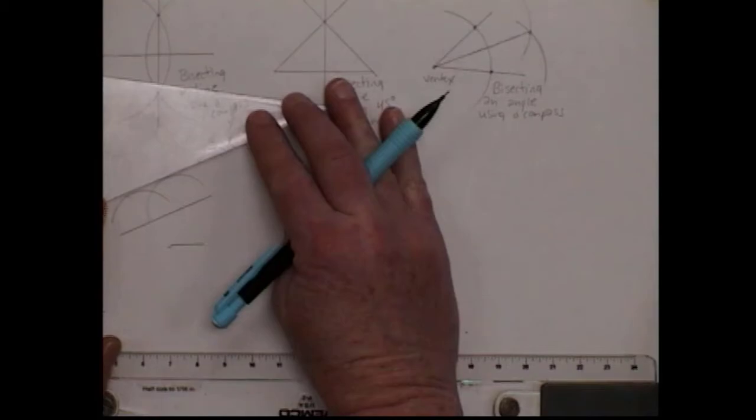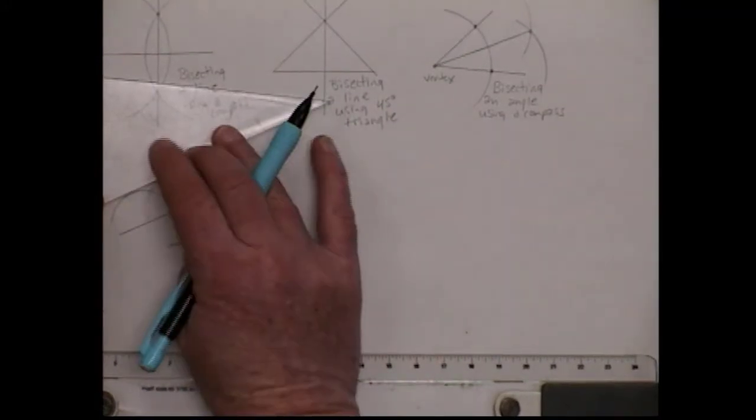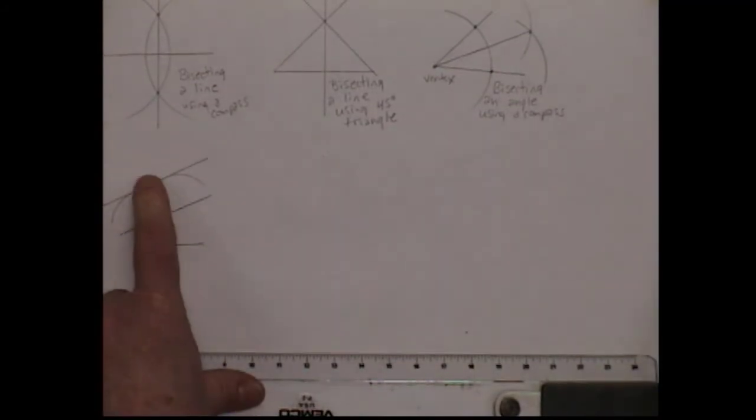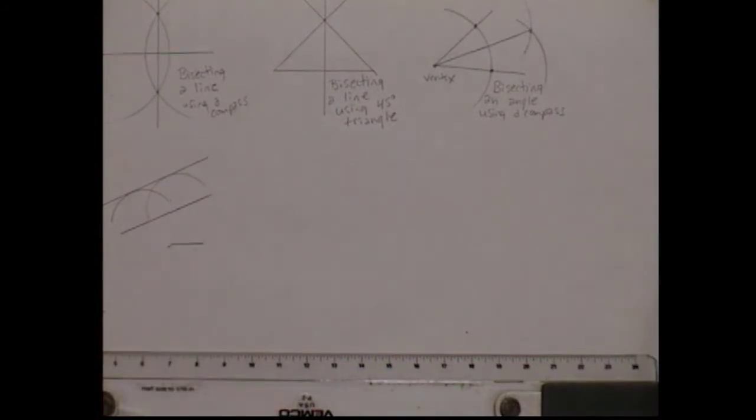So we're going to put our straight edge tangent to the tops of those circles. Then make sure you're just touching it at the very top at just 1 point. That's what tangent means. And then we're creating a line. Once we have it lined up tangent, then we can create the line. So now we have a line that's parallel to the other line at this given distance.